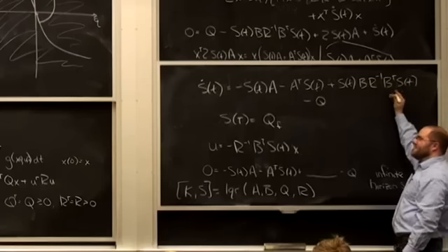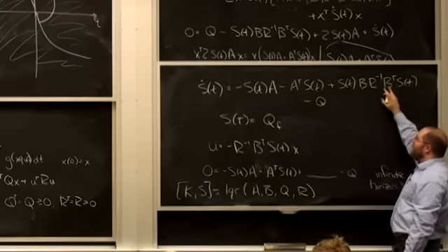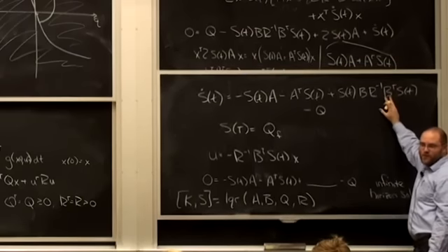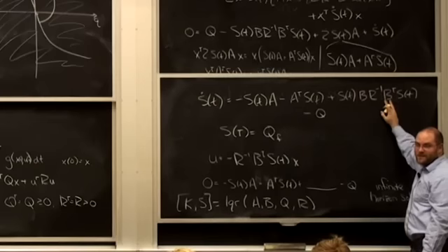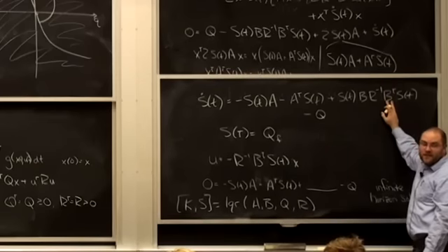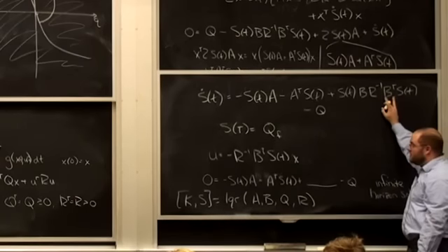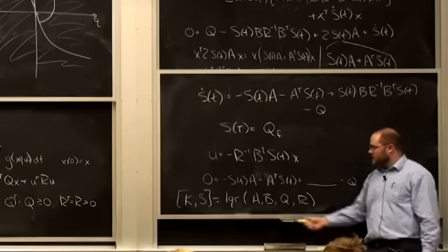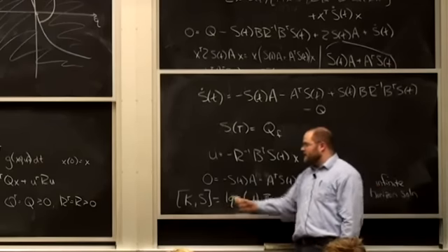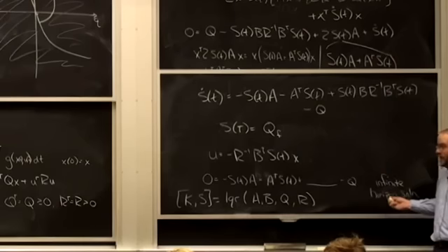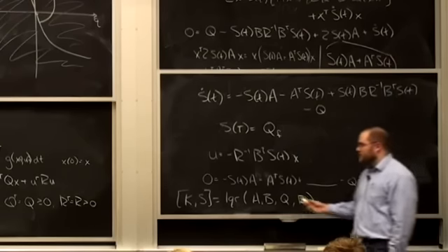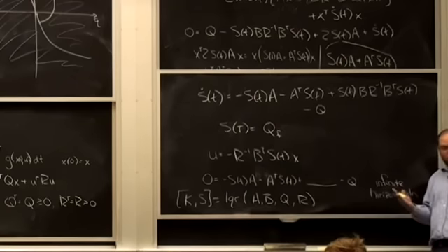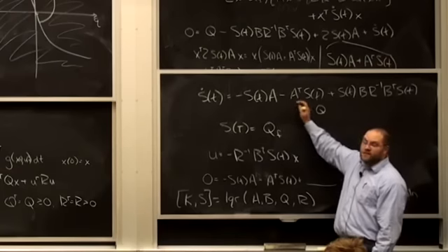But this is a Lyapunov equation again. It's so famous, it comes up so pervasively that people have really good numerical tools for solving it. So MATLAB's got some nice routine in there to find S. When I call LQR with the dynamics and the Q, R, it gives me exactly the infinite horizon S and infinite horizon non-time-varying K. If you need to do a finite horizon quadratic regulator, then you actually need to integrate these equations yourself.